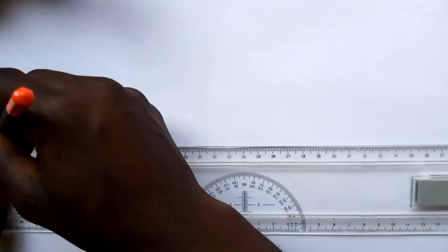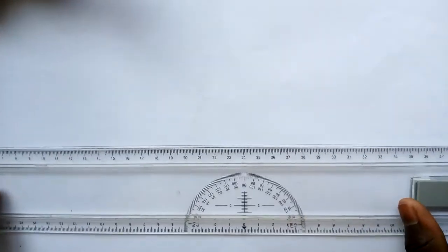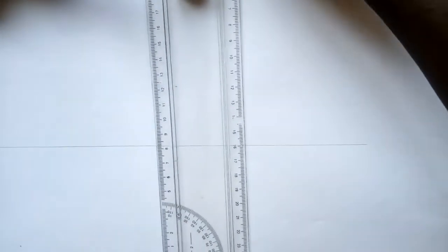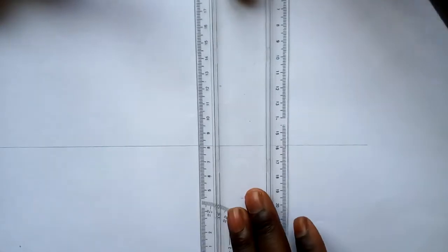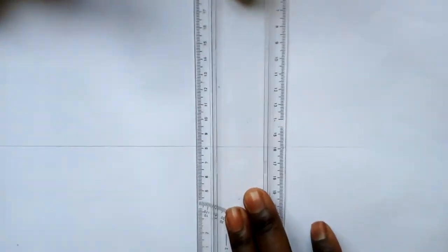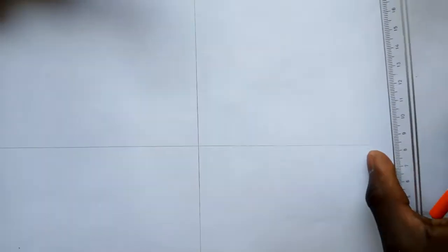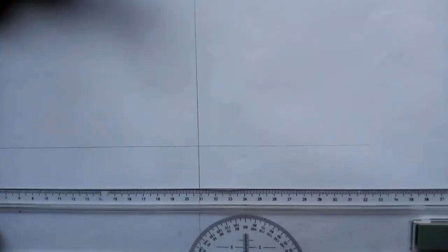Yes, so you begin by drawing the center of the circle, like that. And also you make the center on the other side. All these lines have to be construction lines. Okay, so my circle, the diameter is 54, so the radius is 27.